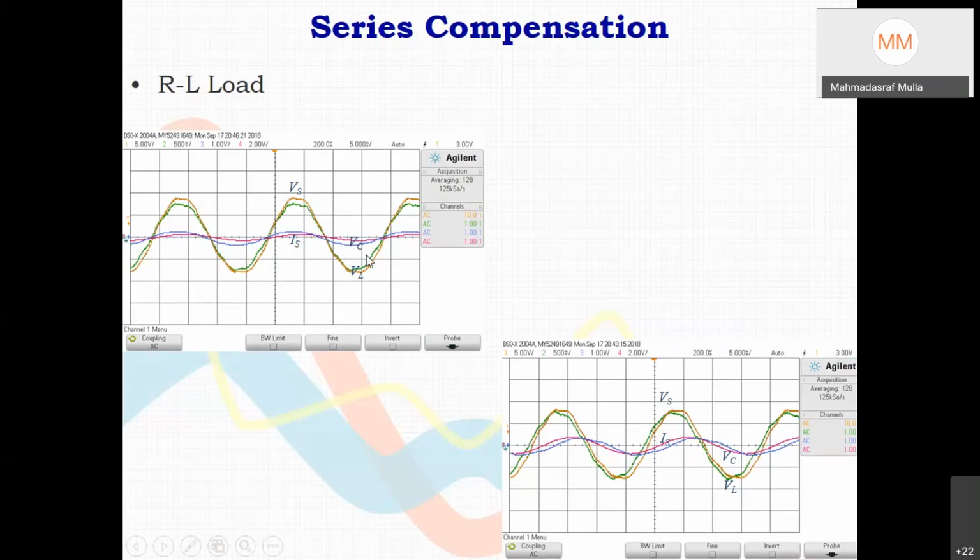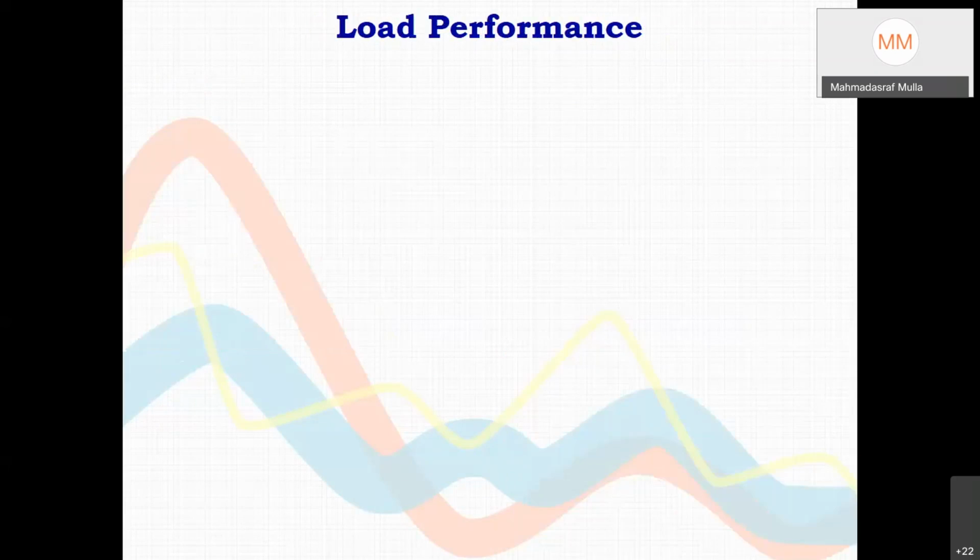For that we are injecting some voltage; VC is the injected voltage, and it makes 90 degrees with respect to current. So it is only reactive energy that this unit is processing, and without any supply, through a capacitor and inductor we can design this unit. Only reactive power it can support.